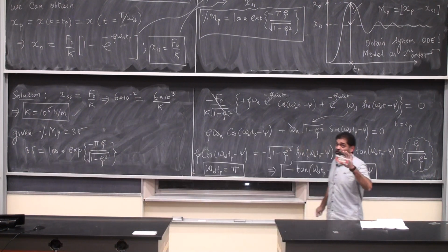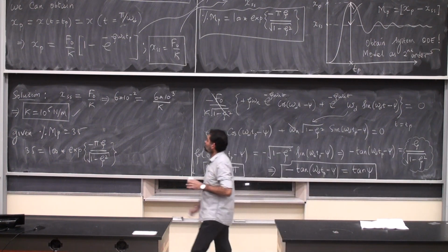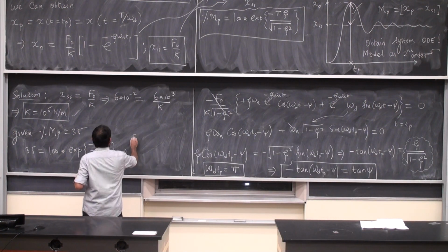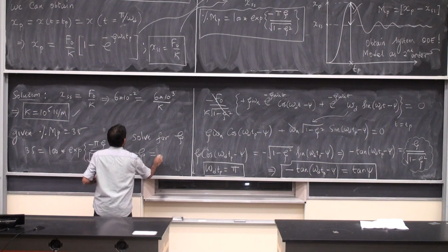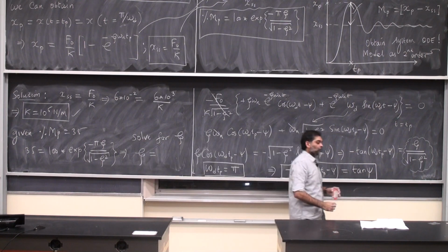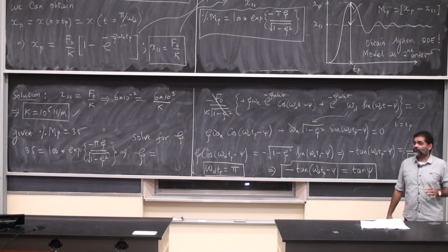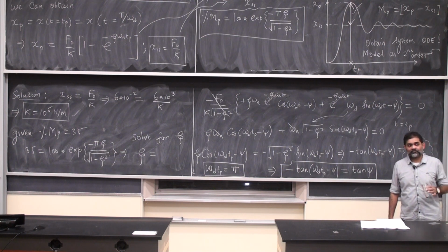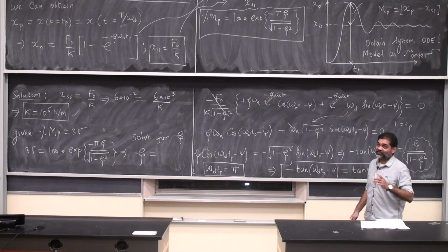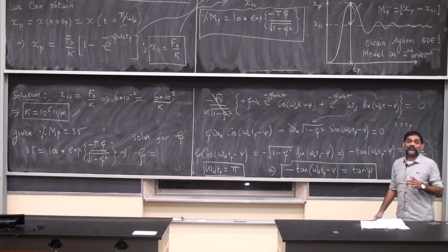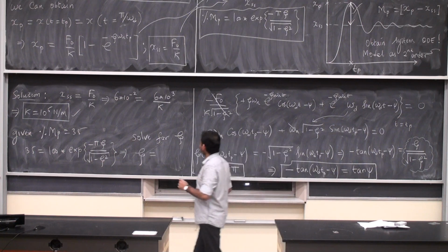Whenever you see an exponent, what do you do? You take the natural log on both sides. You can lose the exponential term. So solve for zeta. What should you end up getting zeta as, approximately? Somewhere less than 1. Beautiful, something less than 1. If you get something more than 1, then essentially something is wrong. This is all garbage. So I have zeta as 0.32.